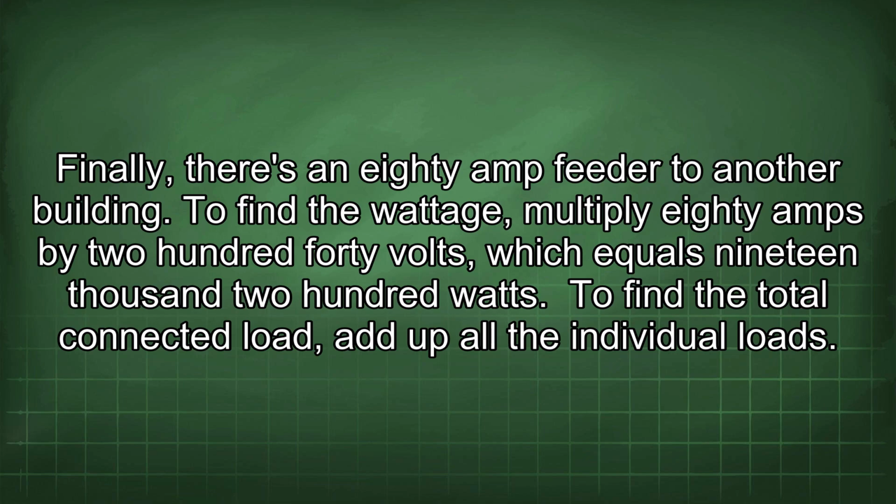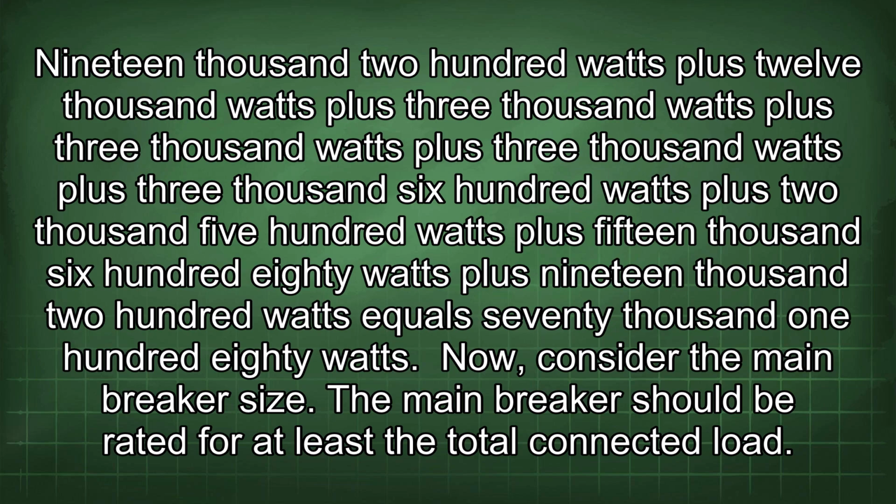To find the total connected load, add up all the individual loads. 19,200 watts plus 12,000 watts plus 3,000 watts plus 3,000 watts plus 3,000 watts plus 3,600 watts plus 2,500 watts plus 15,680 watts plus 19,200 watts equals 70,180 watts.